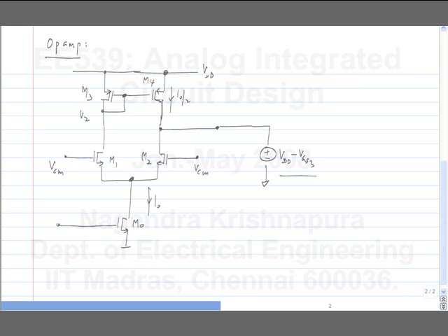So I do this, then I can measure the short circuit output current of the transconductor. I can measure the output resistance of the transconductor. Then I will have everything I want to know. Okay. Then I can go ahead and calculate the voltage gain if I want to. Right. So first let's calculate the transconductance. That is, I excite the input with a small differential increment. And I want to calculate the incremental current I out.